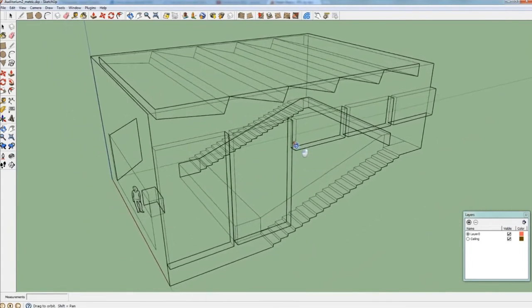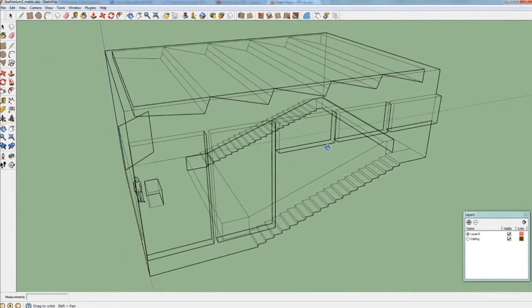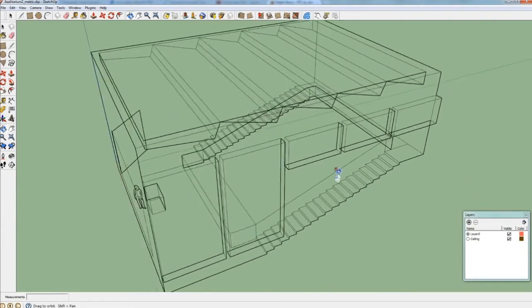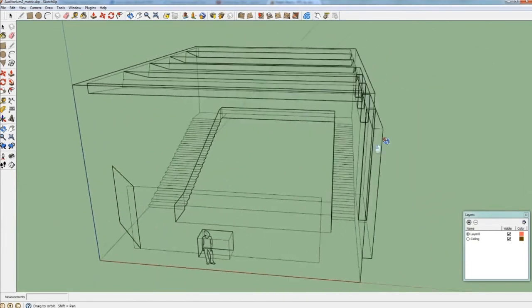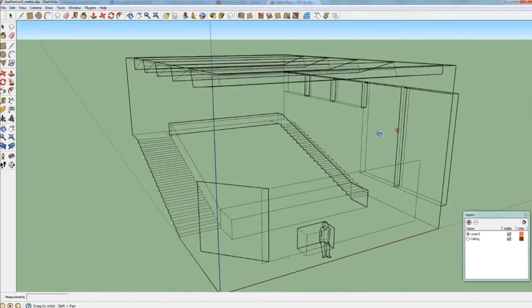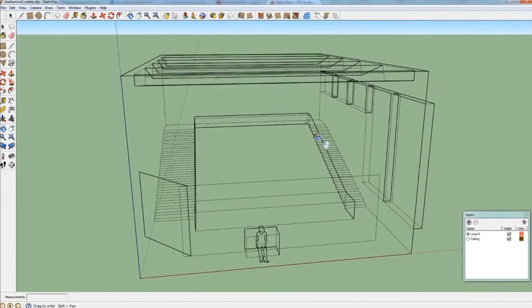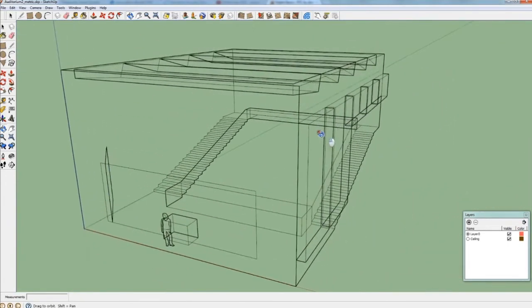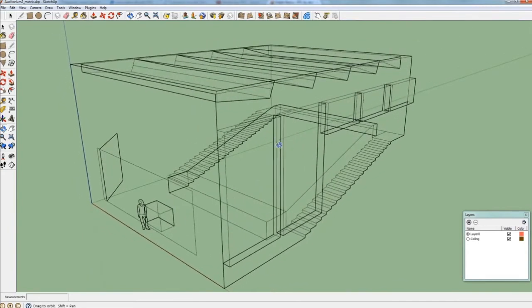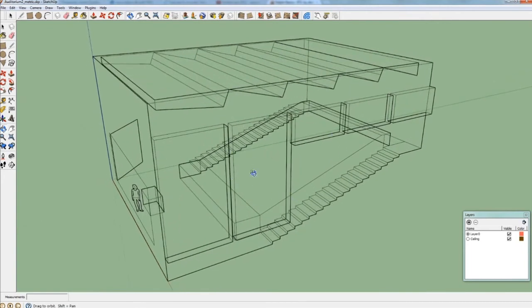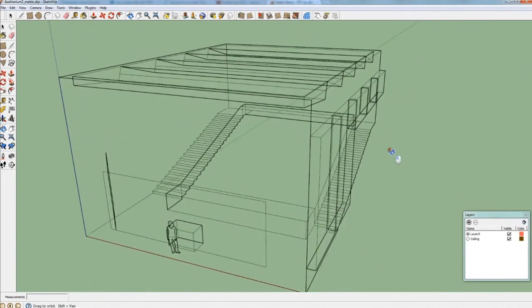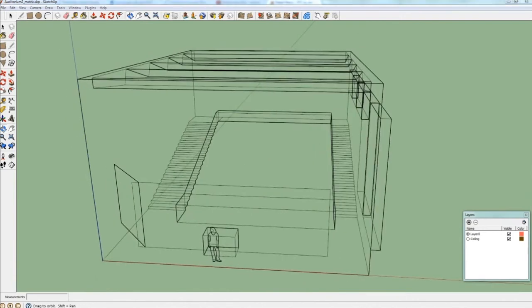On the other hand, Odeon is a geometrical acoustics based software, so therefore it cannot predict so accurately such complicated diffraction phenomena. And then the overall result is much worse than if you model with just a flat surface and assign an appropriate scattering coefficient.